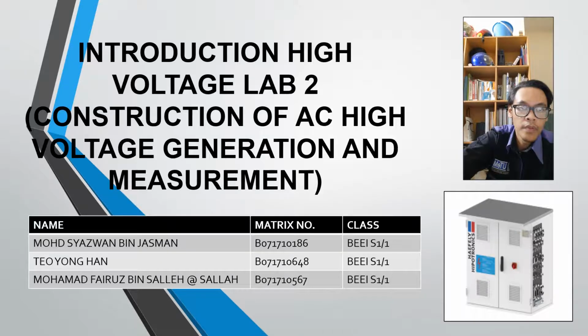Therefore, the following steps must be complied with, which are divided into 4 sections. The first section is about identifying the correct apparatus for the hipot test, the second section is about assembling the AC generation and measurement system, the third section is about fixing all grounding termination points, and the fourth section is about neatness and cleanliness.